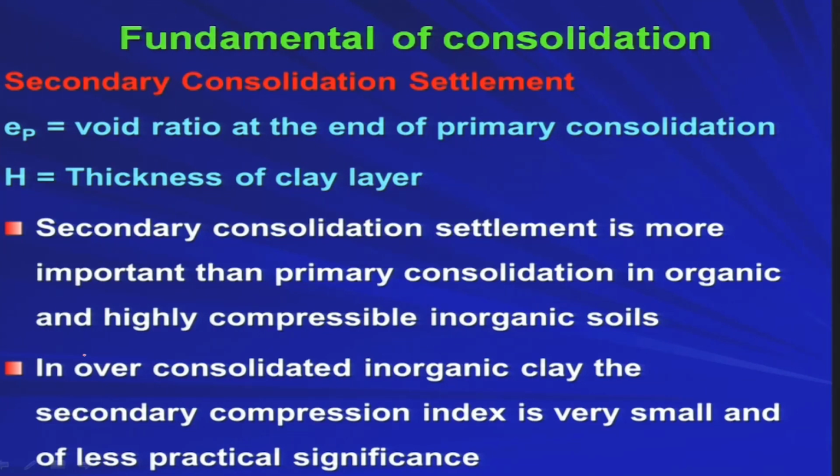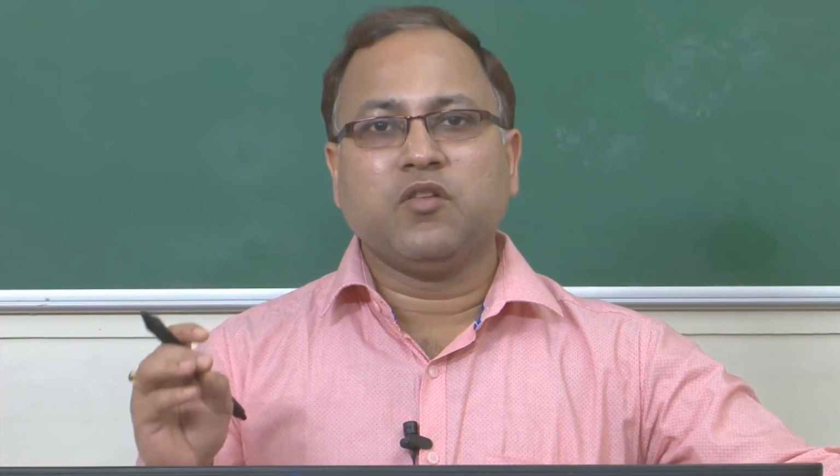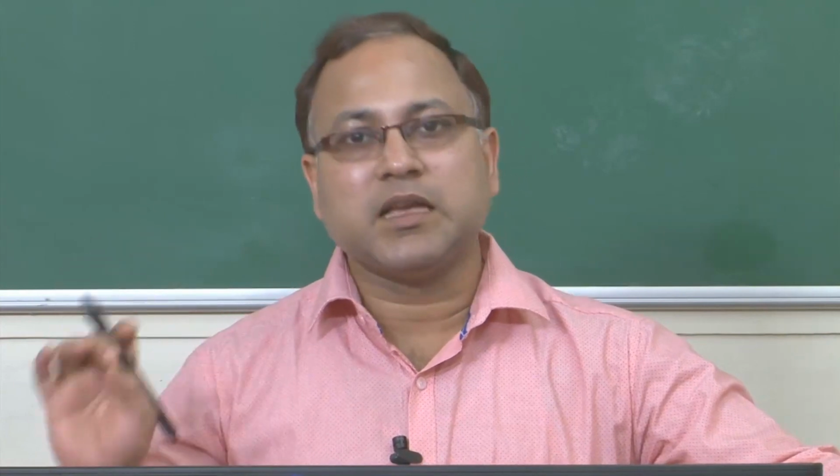So, that is why people generally, for most of the general cases, only calculate the primary consolidation settlement and based on that they design the whole structure, right. I mean, the secondary consolidation will be much lower than the primary consolidation settlement in case of normal soil, right, over consolidated normal soil. So, in case of that type of soil, your primary consolidation has to be given more emphasis than the secondary consolidation. So, that is why people are not that much interested to find out the secondary consolidation settlement, because it depends on time.